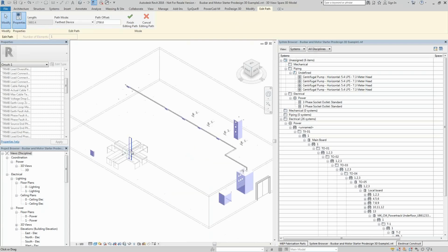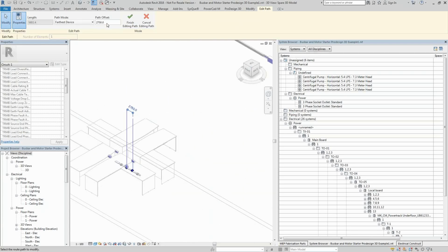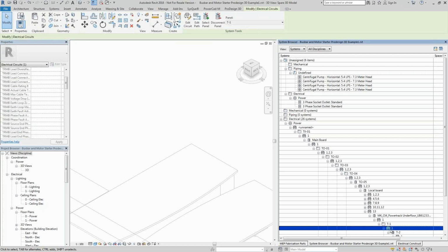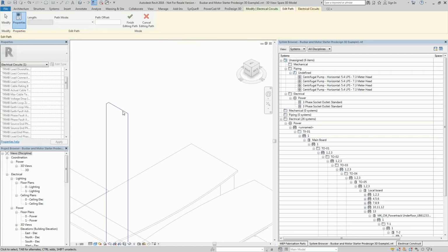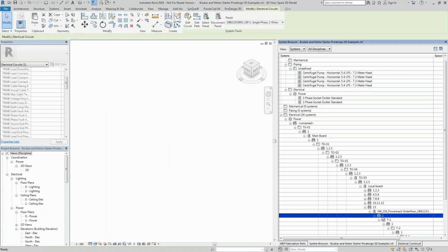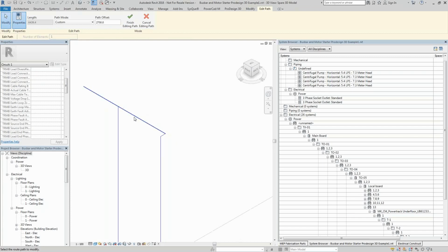There's not too much raising or lifting of the devices. Oh, we should check the offset on that, so we want that to be 0. Or you're going to get some really weird readings coming through. So we just go into that one. Again, we just want to set that to 0. Just check this one as well.